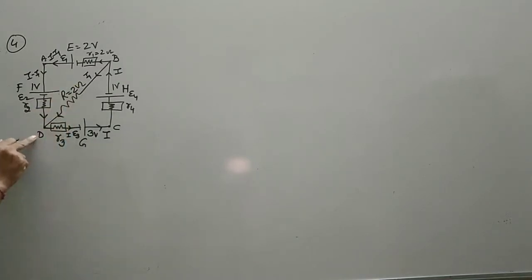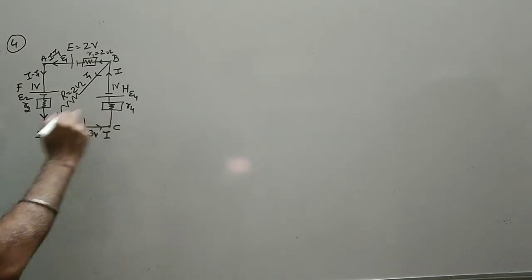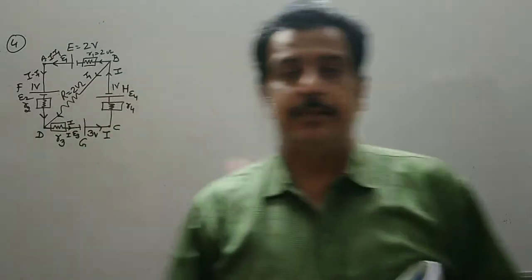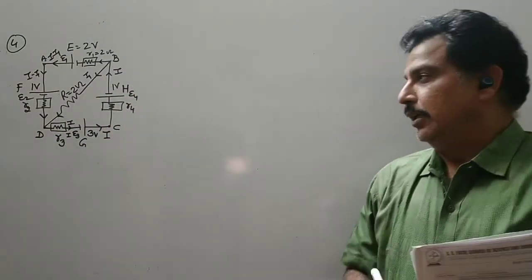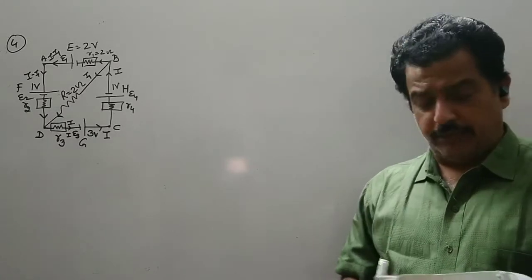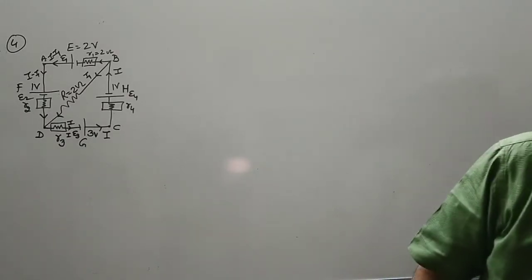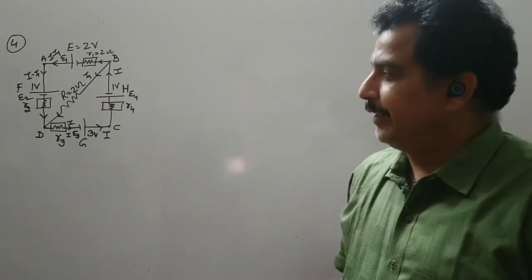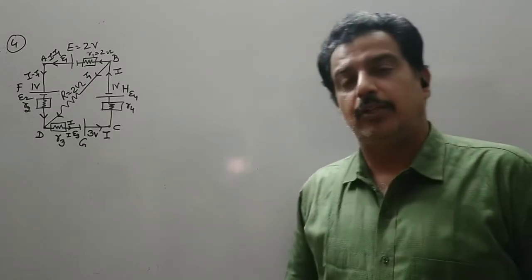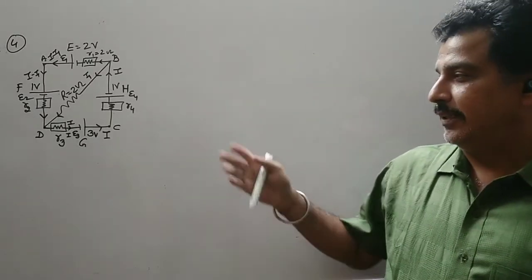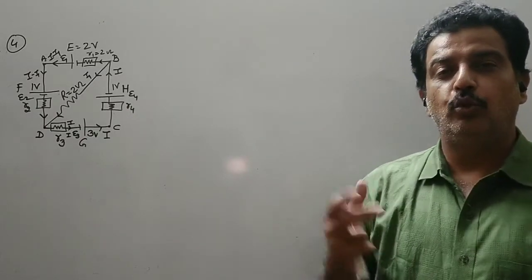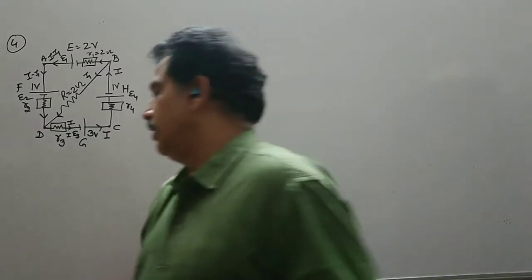So when we apply Kirchhoff's first law at point D, the total again will become I. Whatever amount of current we start with, that amount of current comes back to the same cell. So the distribution is done properly. To find the potential difference between points B and D, we should determine the I1 value. Now in this distribution there are 2 unknowns, one is I and the other is I1. So at least we need 2 loops to determine these values.